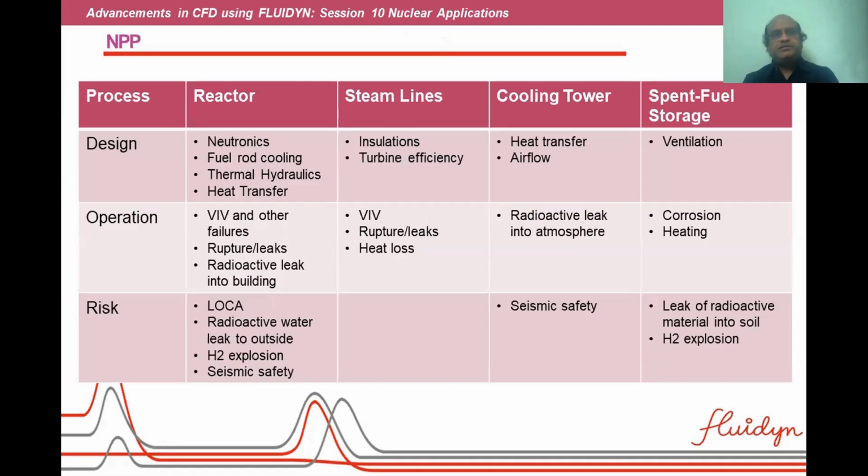If you look at the processes that typically occur in nuclear plants, and where we had applied computational fluid dynamics to analyze the designs, or to analyze the operating conditions, or to compute the consequences in case of an accident, you can see that there are many things like neutronics, that is transport of neutrons and their absorption, subsequent heating of surrounding liquid metal circuits, fuel rod cooling, and thermal hydraulics, that is heat transfer and multi-phase flow, vortex-induced vibration of pipelines, ruptures or leaks, radioactive leak and transport of radioactive nuclei.